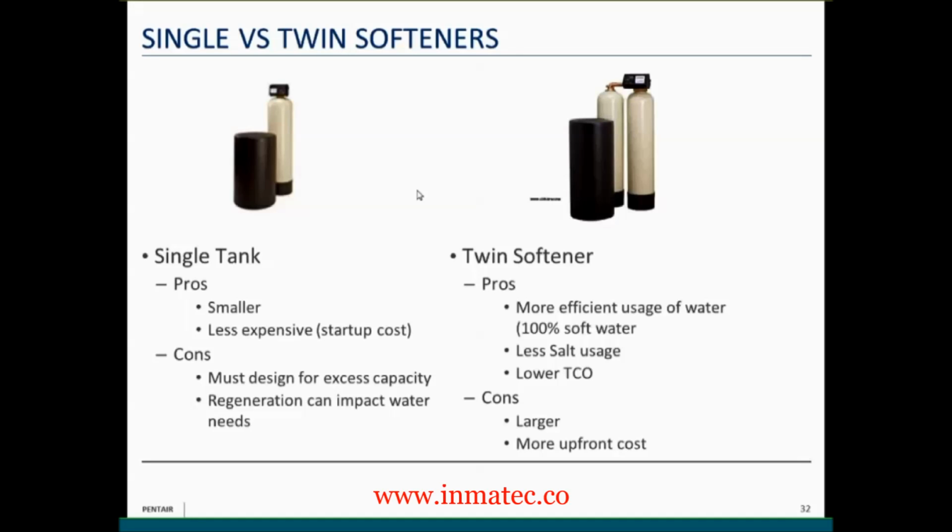So we have to set aside 10 to 30% of the capacity of this resin bed to compensate for fluctuations in hardness, because water softeners are metered by how much water goes through them, not the hardness that goes through them. So this unit could regenerate at any given point in time during a day, once it has gone through the amount of water it needs before it regenerates.